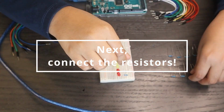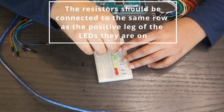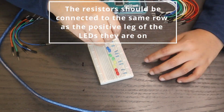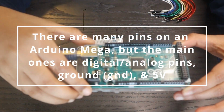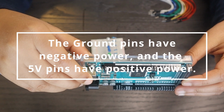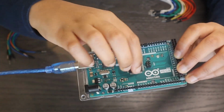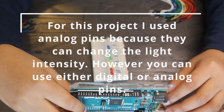Now, let's connect the resistors. Connect the resistors on the same row as the positive leg that the LEDs are on. And remember, there are several pins on the Arduino Mega, but the main ones are digital, analog, ground, and 5V. The ground pins have negative power, while the 5V pins have positive power. For this project, I used analog pins, but you can use digital or analog.